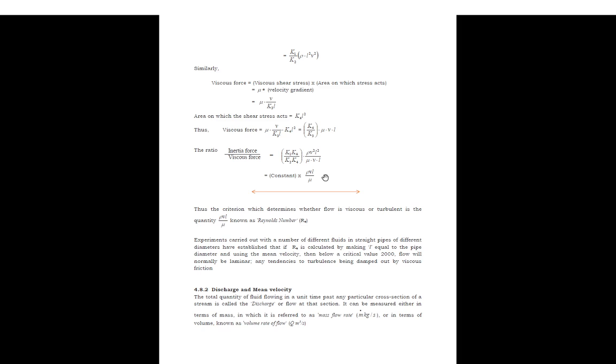The description of categorizing flow as either laminar or turbulent was proved by a gentleman called Reynolds, and he called it the Reynolds number. The Reynolds number looks at the density, the velocity, the characteristic length, how long your conduit is where your water is passing, and also what we are calling the coefficient of dynamic viscosity, which we defined earlier.